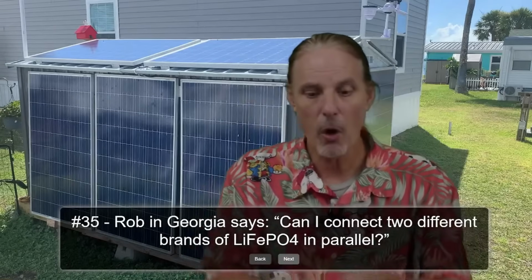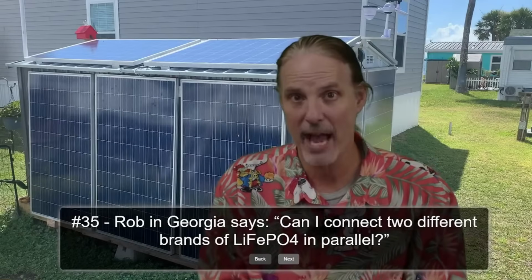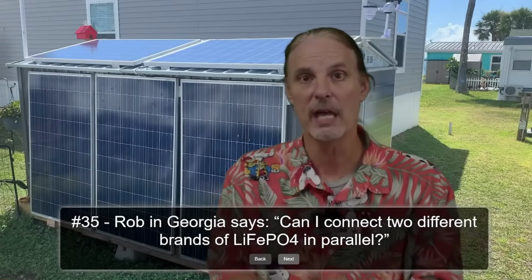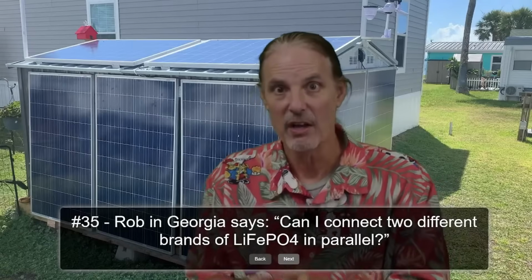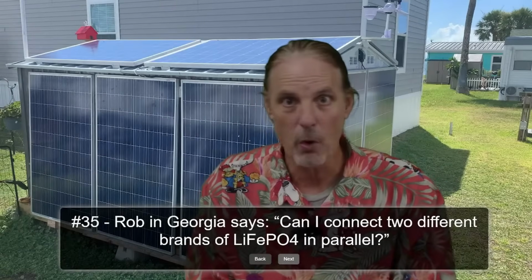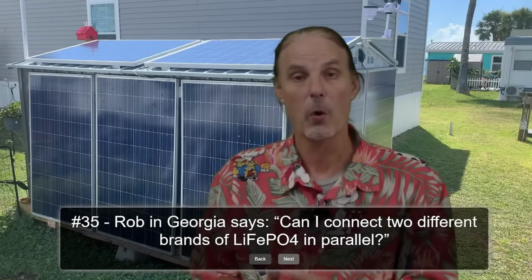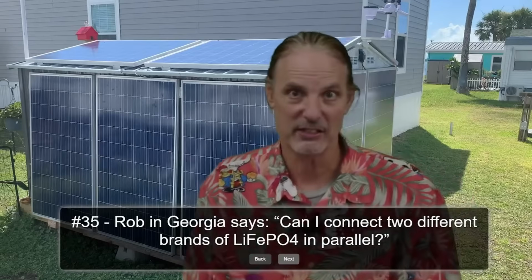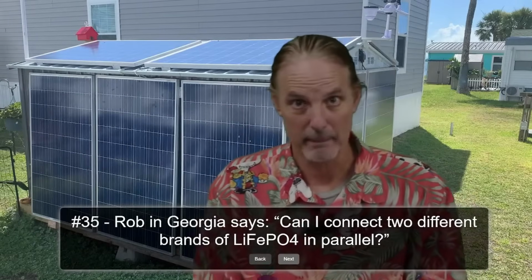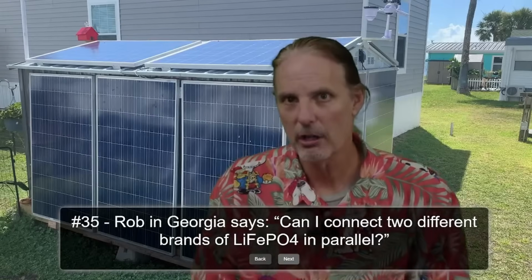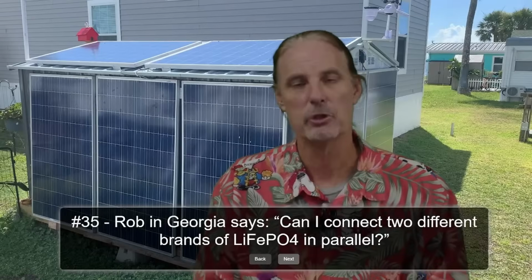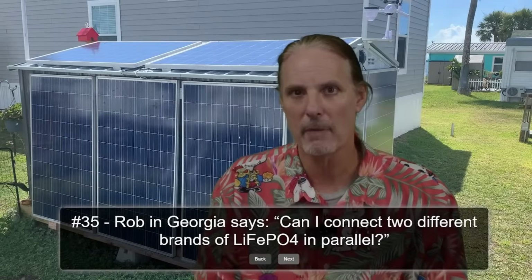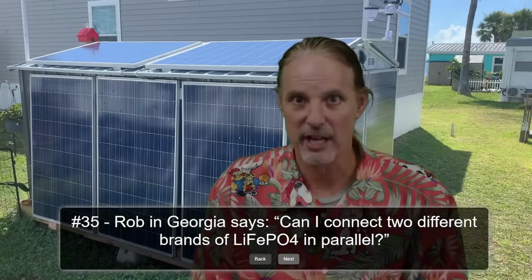They need to all be consistent batteries. In other words, they need to all be either lithium iron phosphate, 16 cell, nominal voltage 51.2 volts, or they need to all be 15 cell lithium iron phosphate batteries. So as long as you follow all those rules, yes, you can safely do it, but you have to do the homework and make sure that you have the right setup.